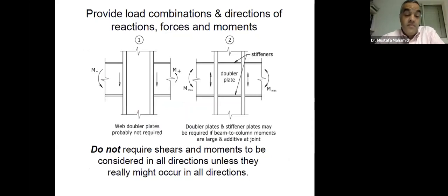Provide load combinations and directions of reactions, forces and moments. Of course, if you have both directions, it's both directions, in the case of, for example, seismic. But if it's one direction, just provide the direction. Also provide the forces and provide the moments.